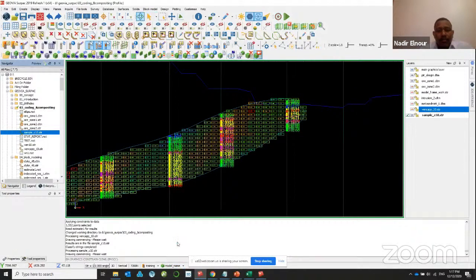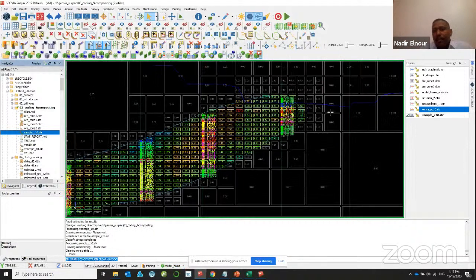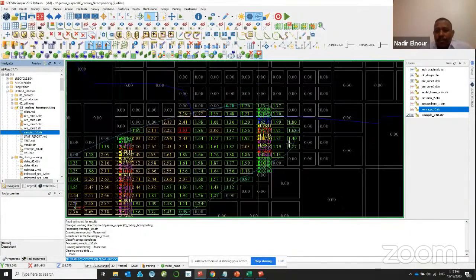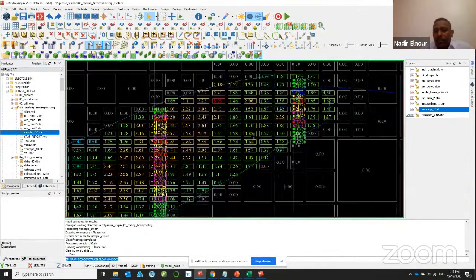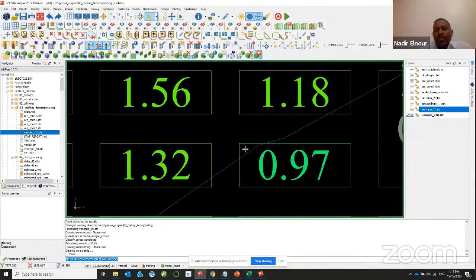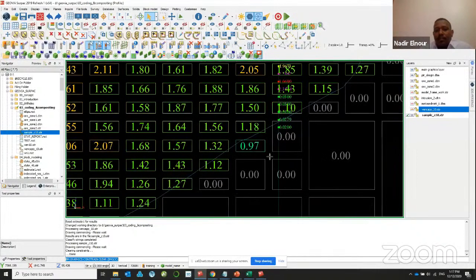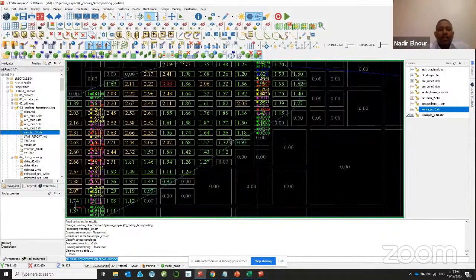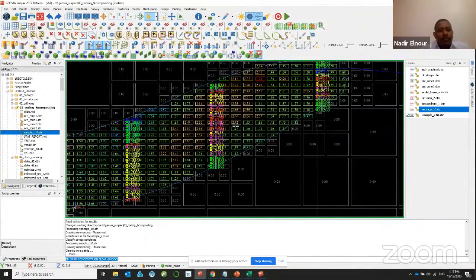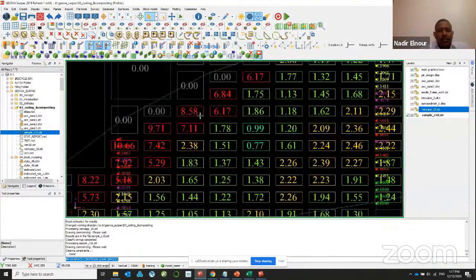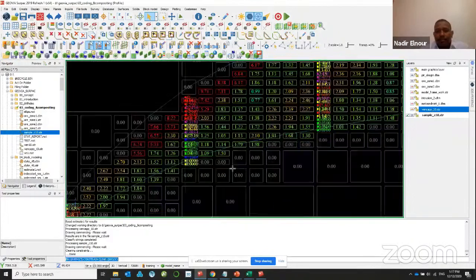As you can see, if I remove all this constraint, the grade boundary is not populated inside this one. Because of the block size, I have smaller blocks. Maybe this block is 5% inside, but it already gets resulted. But if you have good sub-blocks, for example like this one, you need to select a smaller sub-block, so you will get actual results. Then this is your estimation. You can see this is your high grade vein, and this is your estimation.